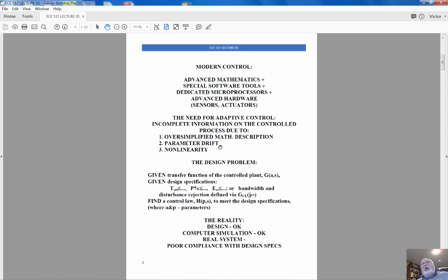But if we change the regime of operation, we would change the point of operation, and the point of operation will move along the nonlinear characteristic, and we will be using linearization at a different location, and obviously it would be a completely different linear characteristic that we will use to approximate the system.